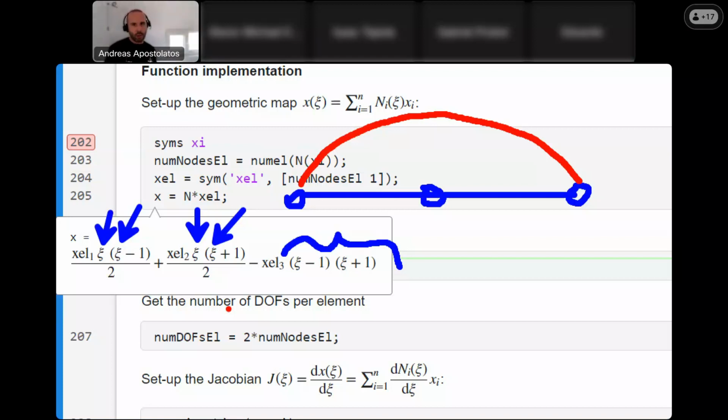If you have a parabola, a quadratic polynomial, it cannot be uniquely described by two nodes, right? You can have an infinite number of parabolas that pass through two nodes. That's why we're not using that, because otherwise our stiffness matrix would have been singular. Whenever you hear that an infinite amount of polynomials can be used to interpolate two nodes or more, it means immediately that our stiffness matrix is going to become singular. Hopefully that answers the question.